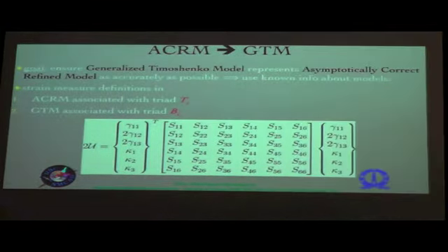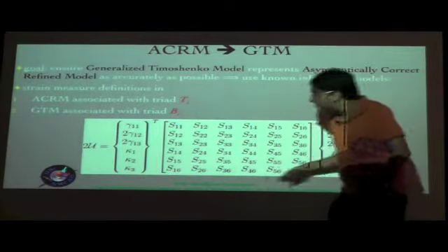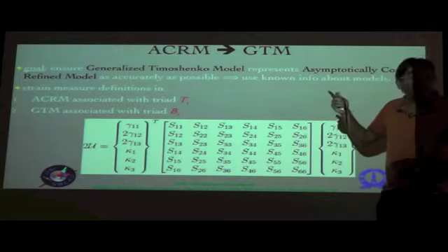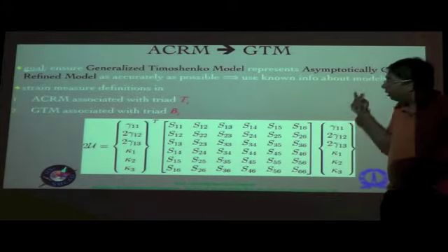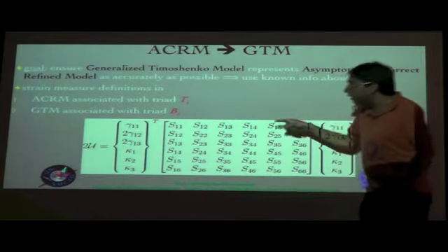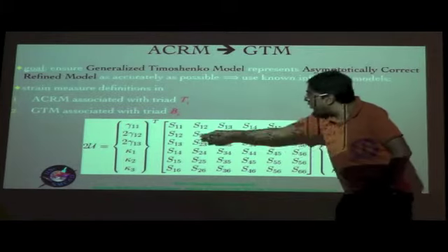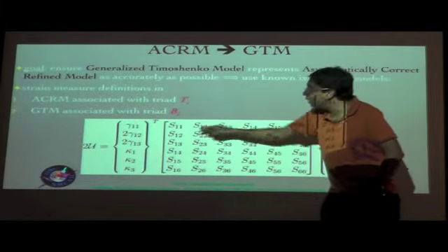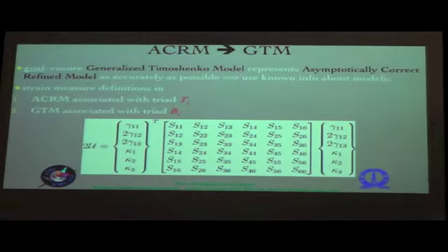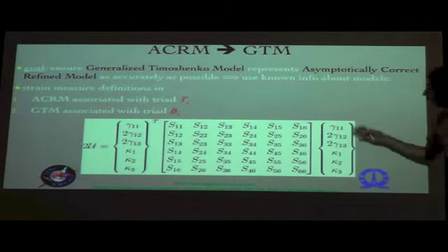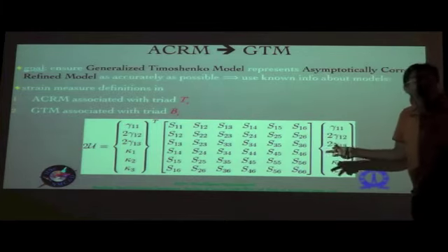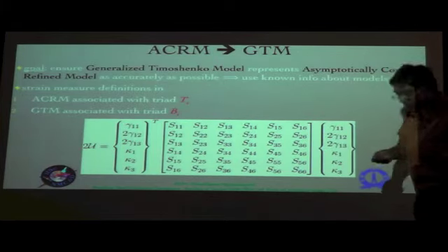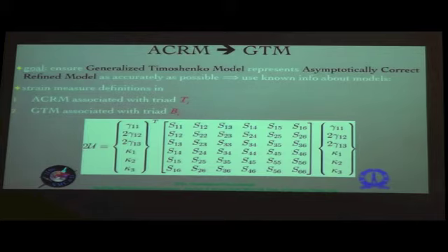So that is eventually going to lead to a matrix like this. Instead of the S bar matrix, which was a 4x4 matrix, you have an S matrix, which is now a 6x6 matrix, where you have additional rows and columns in the second and third places, as you see, associated with gamma 1 2 and gamma 1 3, and in turn corresponding to the work conjugate would be F2 and F3, the shear forces. So with this, we will complete the cross-sectional analysis.